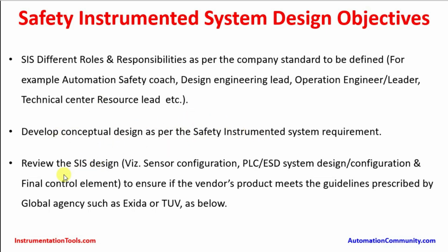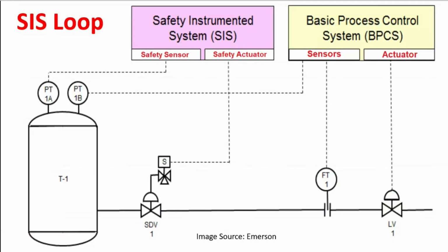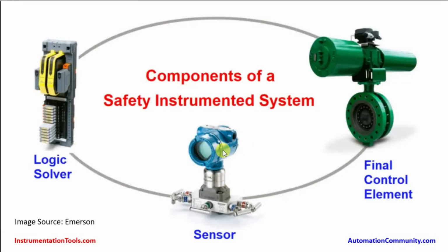And review the SIS design, like SIS sensor configuration, PLC or ESD system design and configuration, and final control element. Like what we saw in this one, here we have the sensor, the logic solver, which is a PLC, programmable logic controller, and this is the final control element.